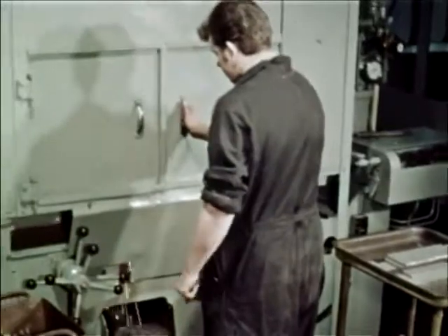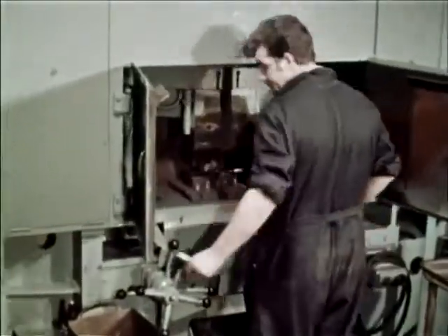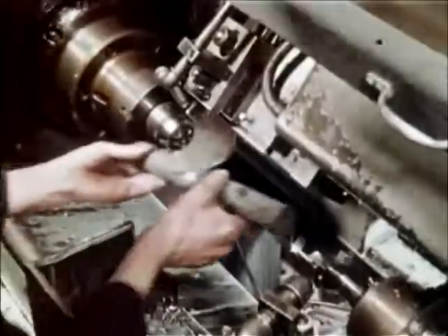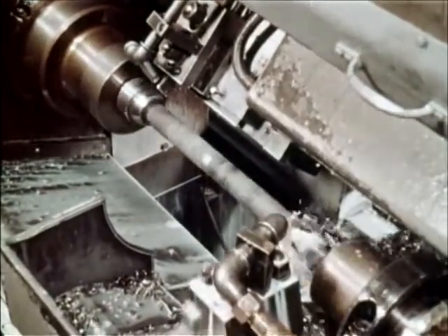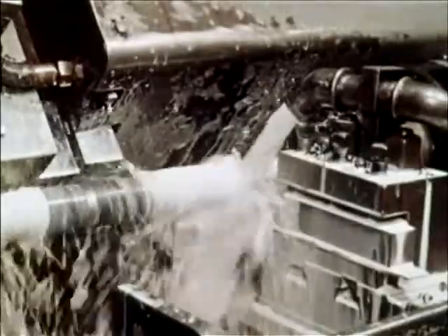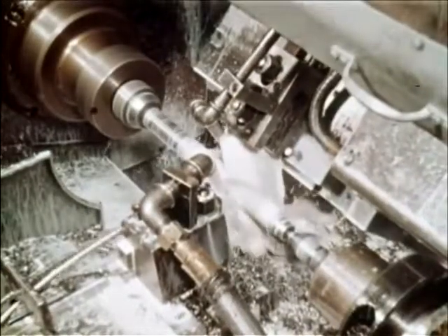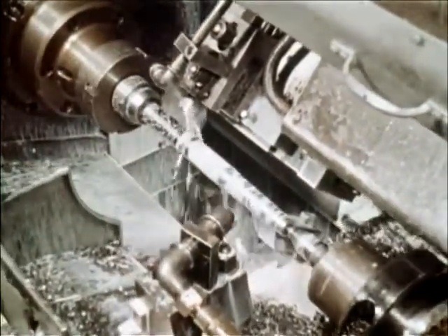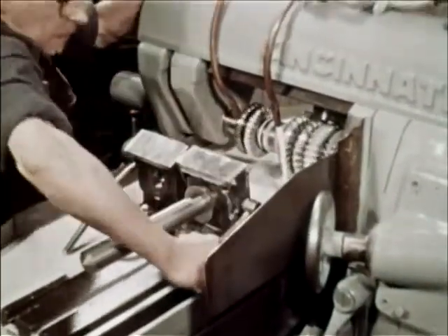Taper shank drills have a high-speed steel body which is flash butt welded to carbon steel for the shank. Copy lathes are used to turn the shank and body simultaneously. Milling machines are then used to produce the tang and the flutes.